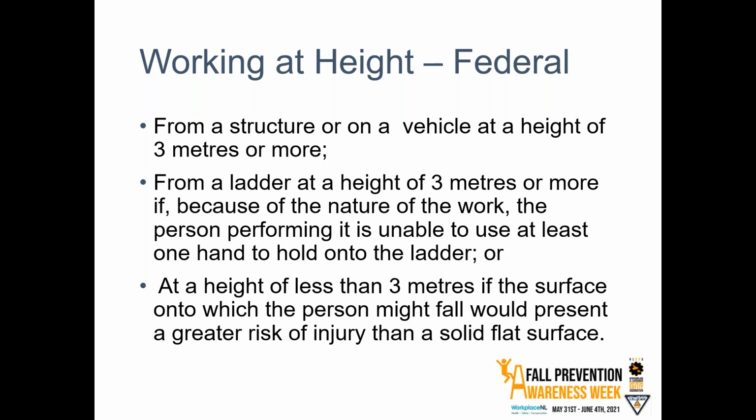And that's a tricky one to enforce. I got to say, I've had some issues with trying to get people to tie off on ladders, especially when you're moving ladders around a lot to do work. Say maybe you're doing electrical work and you're shifting the ladder every few feet. That can be very, very tangly. So certainly it's a better idea to maintain the 3-point contact if possible.